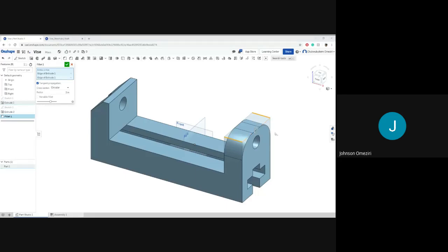Okay. So you click on the fillet, then choose the 2 edges there, then set the number here to 3. Then click OK. So now that we have this done, we could come here and change the appearance. Usually you could change the appearance, you could change the material. The reason to change the appearance is that when you're combining things together, it'll be easy to identify what it is. You can assign material.